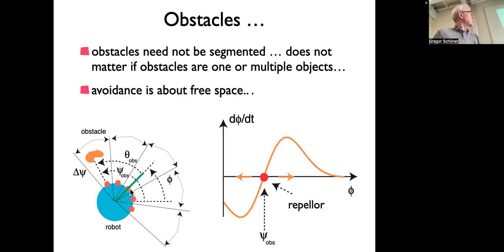The notion would be that each marker erects a contribution to the dynamics. So a little repelling force of that nature that is erected in the direction in space. Remember, this is this coordinate frame in outer space, into which this sensor is currently pointing. So for instance, this sensor is currently pointing in this direction. That's this angle to the world axis. Now the vehicle is heading in this direction at the moment. And so this is the heading. And this is a particular value of the heading when it coincides with the direction in which the sensor is pointing.